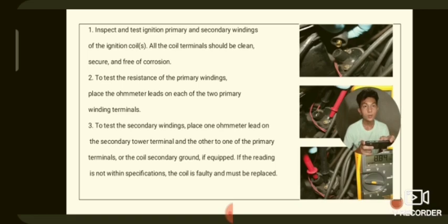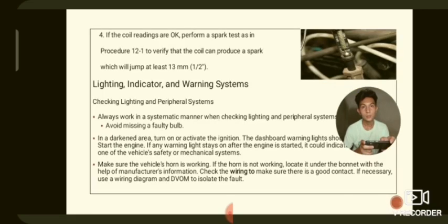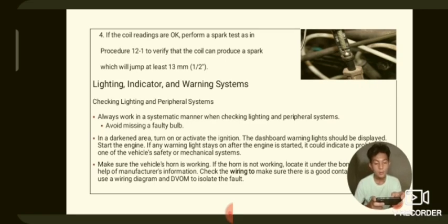Number 4. If the coil reads are okay, perform the spark test as in procedure 1 and 2, verifying that the coil can produce a spark that jumps at least 13 millimeters.